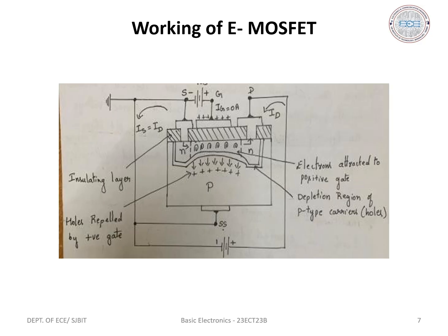Okay. So now let us supply the positive voltage between the gate and the source terminal by keeping the drain and the source voltage as 0. Okay, by keeping VDS as 0 volts, if we supply the positive voltage between the gate and the source terminal here, initially holes are the majority carriers in the p-type substrate.